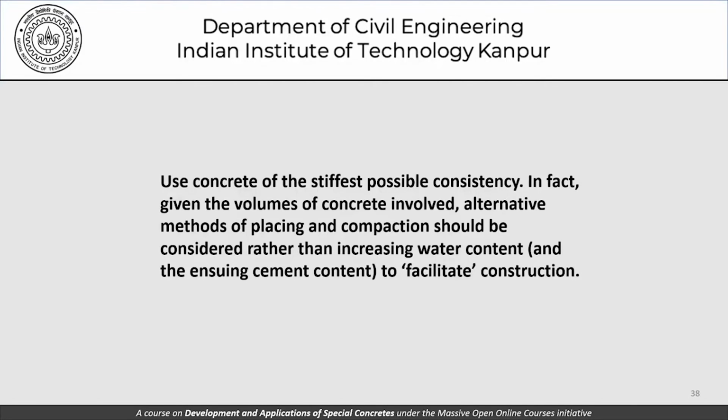Now, this kind of a thought process is exactly at the bottom of our thinking when we try to develop roller compacted concretes. We try to use a huge amount of energy to compact the concrete, which is not possible perhaps using just internal vibrators or needle vibrators as we normally use them. And therefore we work with stiff concretes, and that's what's being said.